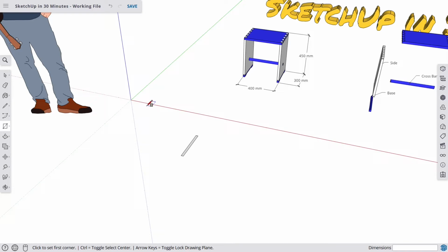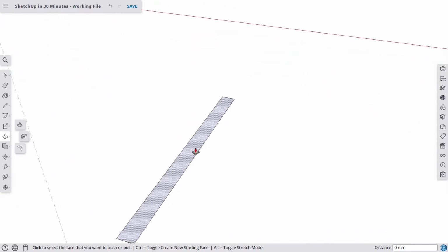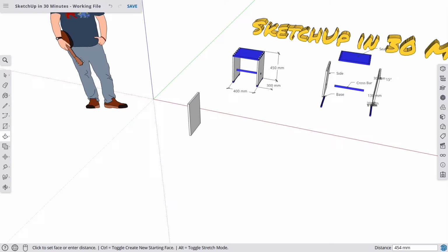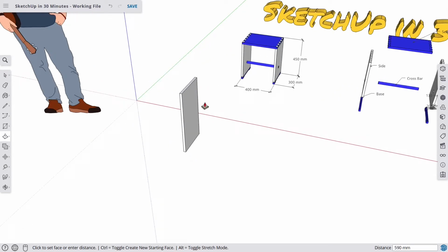But what we need now is we need to pull it upwards. So go to the left side here, you find the push and pull tool. And this is really what makes SketchUp special, because now immediately we can go to this rectangle here. We can click once, don't hold the mouse key. We pull this thing upwards. So in other programs, this is harder, but in SketchUp, we are directly in 3D and we can pull our objects out of the ground.